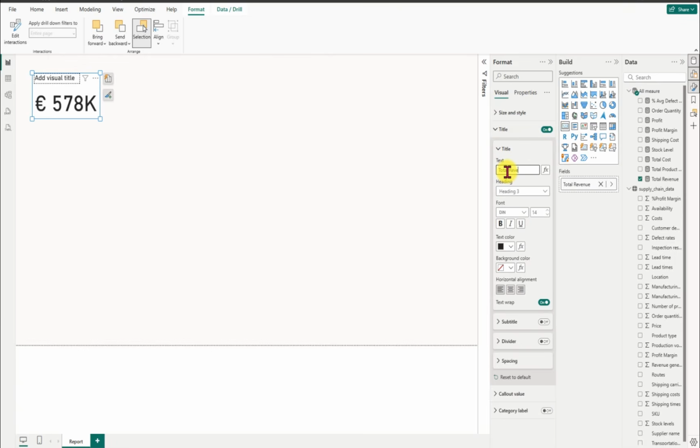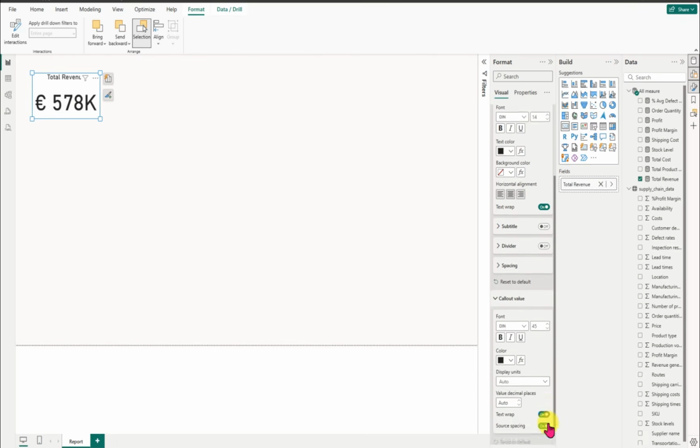So that is the first thing I'm going to do. As you can see, we have it at the left hand side. So I'm going to horizontal alignment. I'm going to make it center. Then I will just have to move down a bit. Then I will go to what we call callout value. This is the callout value. I want it in a simpler way. Then I'm going to just come down a bit. I'm going to have like 35. So that is perfectly good by me.